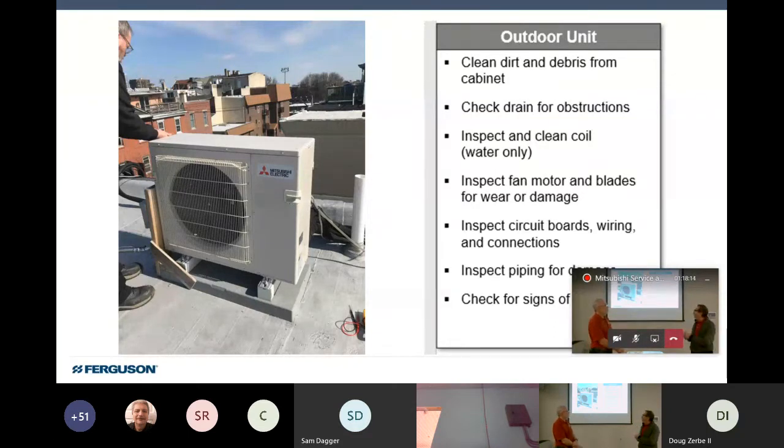And looking at inspection on the piping, Jim, we've seen this already. You will notice that this particular picture is actually on a home in Philadelphia. Not only was our Mitsubishi on the roof, but other apartments that were in this commercial building that was converted over to lofts. There were other units there. Guys are climbing over each other's units to get to this thing. And you will find line sets that have been stepped on, line sets that go over a curb and now have a bend in it, a kink.